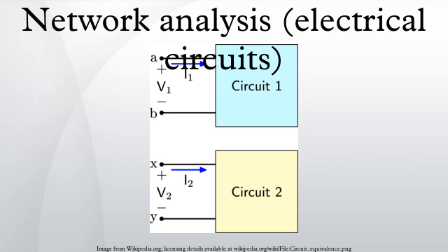Image analysis. Transmission lines and certain types of filter design use the image method to determine their transfer parameters. In this method, the behavior of an infinitely long cascade-connected chain of identical networks is considered. The input and output impedances and the forward and reverse transmission functions are then calculated for this infinitely long chain. Although the theoretical values so obtained can never be exactly realized in practice, in many cases they serve as a very good approximation for the behavior of a finite chain as long as it is not too short.